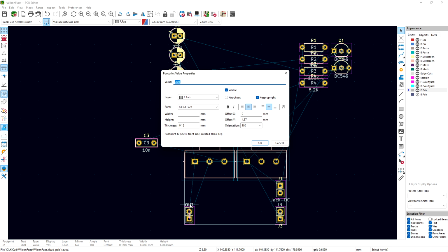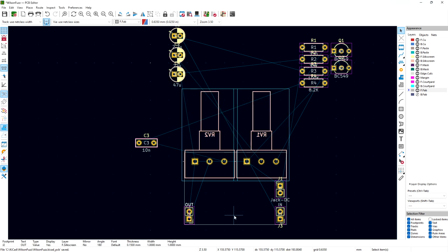So I double clicked here and it appears on my layer. This is unfortunate because in the previous version this was in that grid, you know. So I'm gonna put this on silk screen, okay? And the silk screen layer, we're just gonna hide it. So these are designators. They give you that writing on the board so you know what is there, okay?